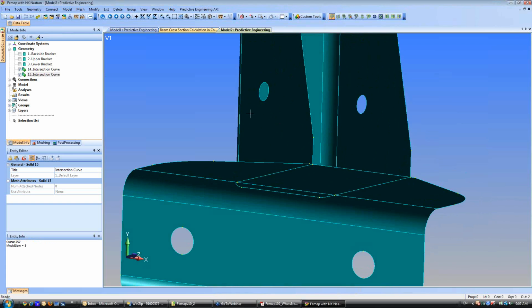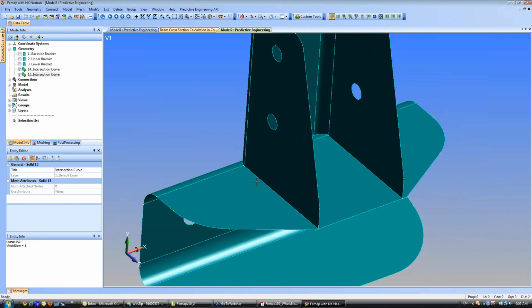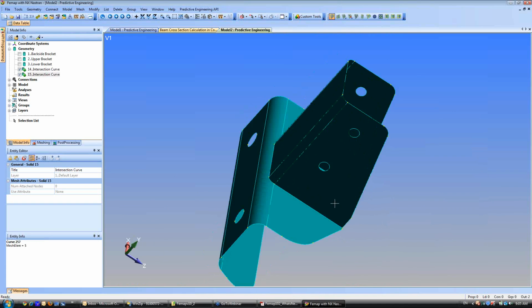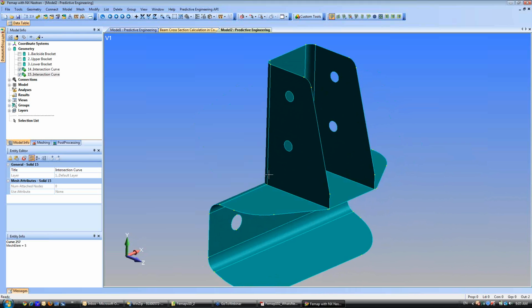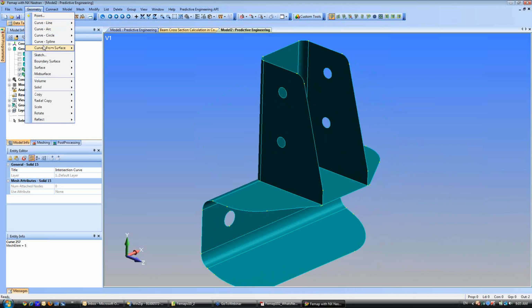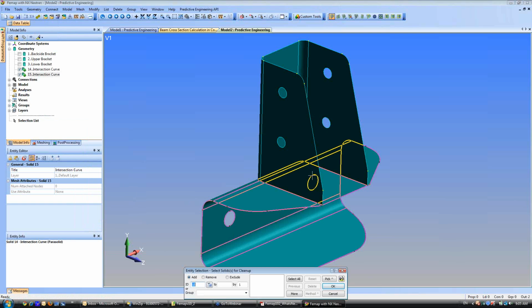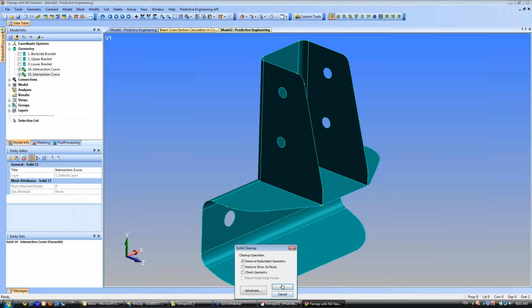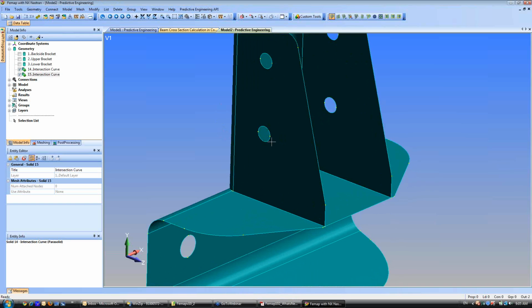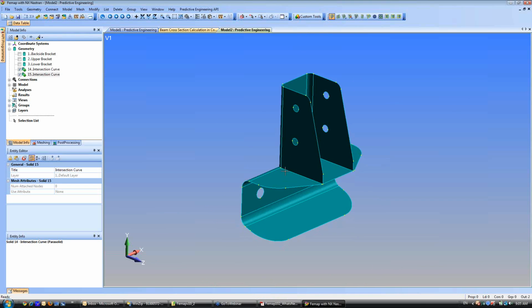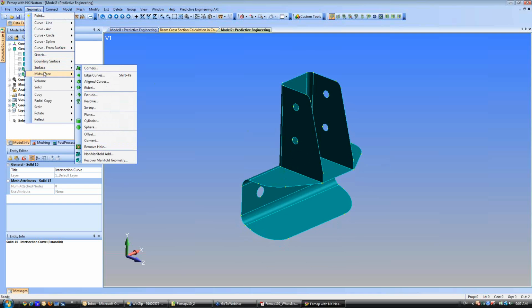So what I'll do is I'll go and extend and slice. And on these operations, you're really hacking on the geometry in the Parasolid engine. And for housekeeping, it's good to go to geometry solid and clean up before you start digging in too deep. And what I'm going to do is pick these 2, and then I'll go back in, remove anything, and check geometry. And if you're really observant, you notice it resplit this curve here. It was 360 degrees. It resplit it, and it just sort of cleans things up.